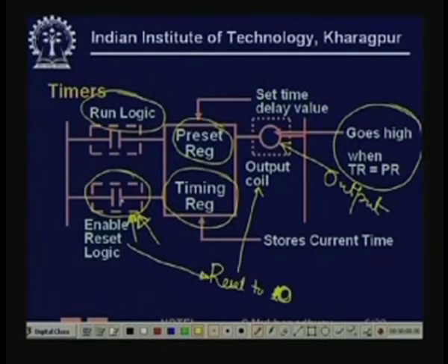For that we can put extra rungs which will program the logic, and when the logic is satisfied or not, that will be symbolized by an output coil. That output coil contact we can put here. So it is not necessary that you always make it a very simple logic, you can make it as complex a logic as you want.